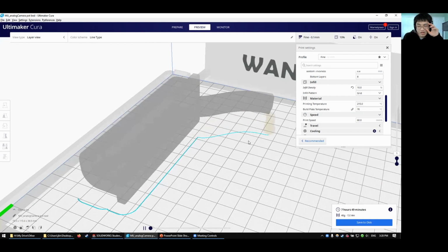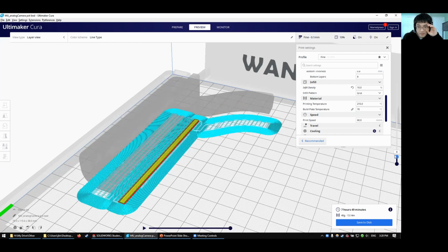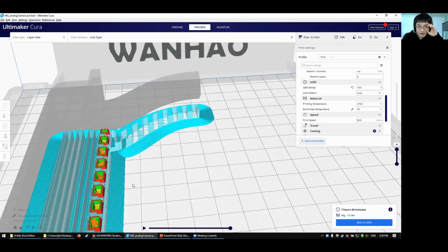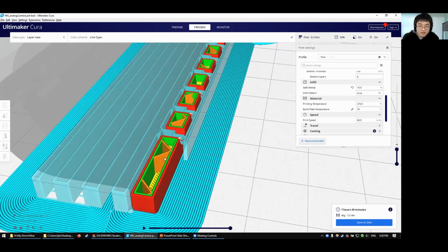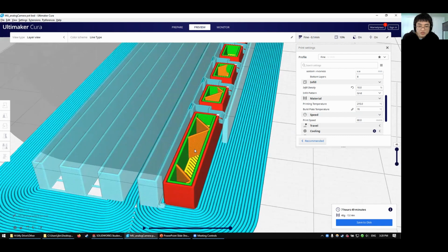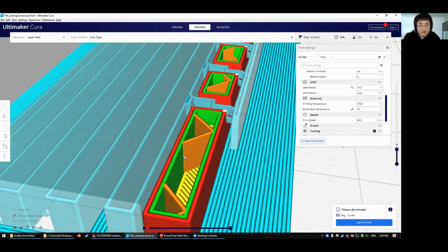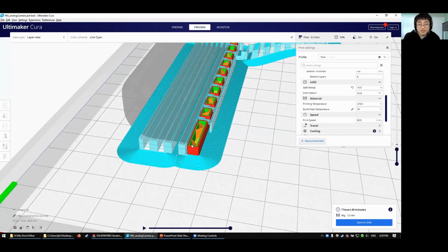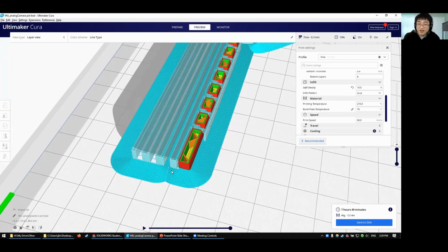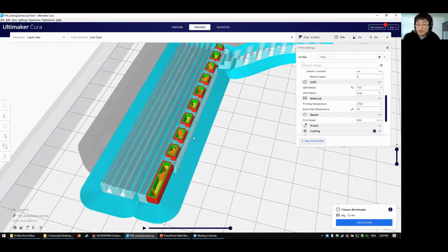What you see here is building a brim around the bottom edge. We will see what a brim is and what other support stuff is later on. But you see it slowly builds it up from bottom to top, as you might expect. And the infill pattern, the controls are different from SolidWorks. It is a grid. It's at 10%, so most of it's hollow, 90% hollow, 10% filled. So this is probably good for prototyping, but if you want it to bear up to any sort of stress, you will want to choose a higher infill.